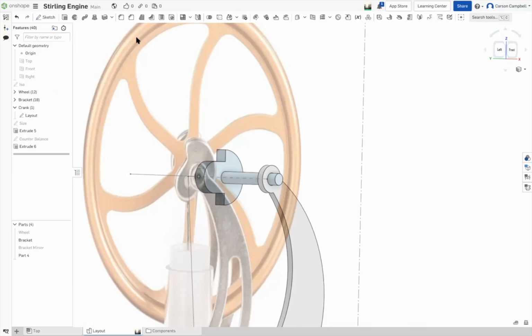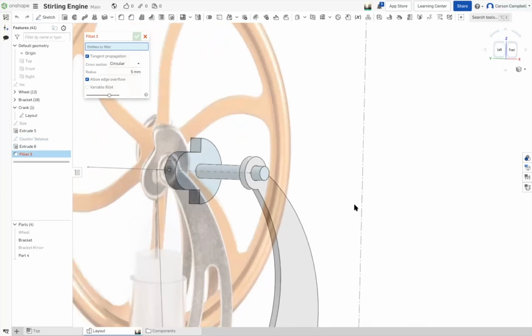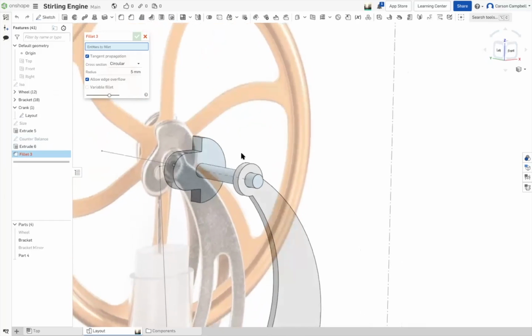The other thing that we want to do at this point is we want to put 4 fillets on that to represent where these things are going. Should I do that inside the sketch, actually? No, no, because look, you're rotating the sketch around and you're going to be farting around with fillets on the sketch. Don't do that. You know what I'm saying? This sketch is a nasty sketch because it has no references, no vertical, no horizontal references, which we normally do, and it keeps them stable. This one's free to spin around in space, therefore let's keep it as simple as possible.